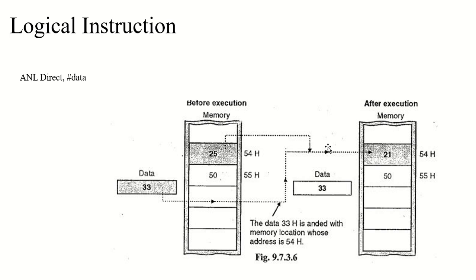The result will be stored in the memory location whose direct address is specified, because we don't have any other option. We are using immediate addressing mode for this instruction, so you don't have any other option except storing it in the memory involved in the operation. This instruction will contain 3 bytes, 2 clock cycles, immediate addressing mode, as you all know.